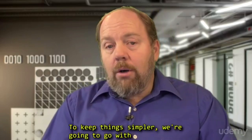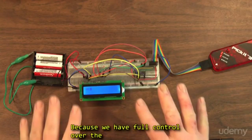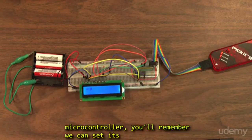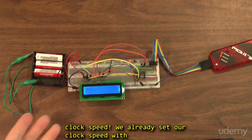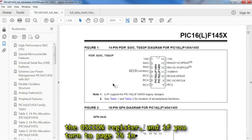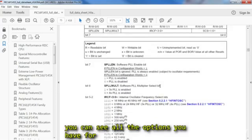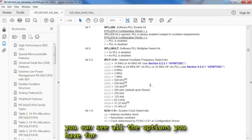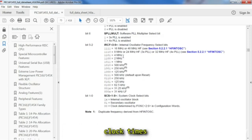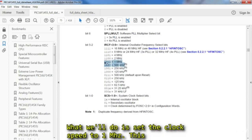To keep things simpler, we're going to go with option number 2. Because we have full control over the microcontroller, you'll remember we can set its clock speed. We already set our clock speed with the OSCON register, and if you turn to page 75 in your PIC data sheet, you can see all the options you have for clock times and how to set up the OSCON register accordingly. Now what we'll do is we'll set the speed to 1 megahertz.